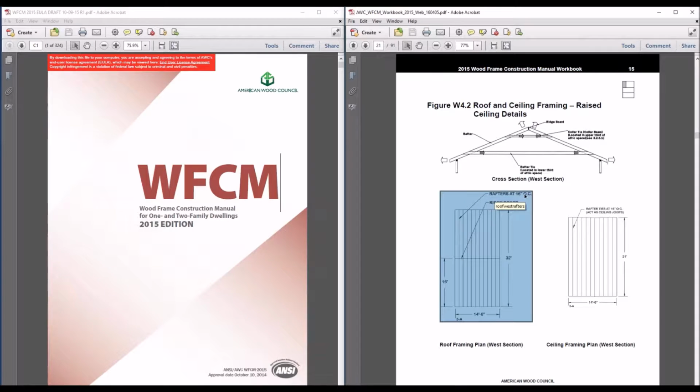One of the things I want to point out, though, is that, again, we've got rafters and rafter ties at 16 inches on center. I think I'm actually going to correct that in this workbook because, as it turns out, we're going to have to go to 12 inches on center to get these to work because of that additional thrust here due to pulling that rafter tie up into the lower third of the span. And so you'll see that in a second. But again, we started at 16. That didn't work, so we're going to end up going to 12 for this particular span.